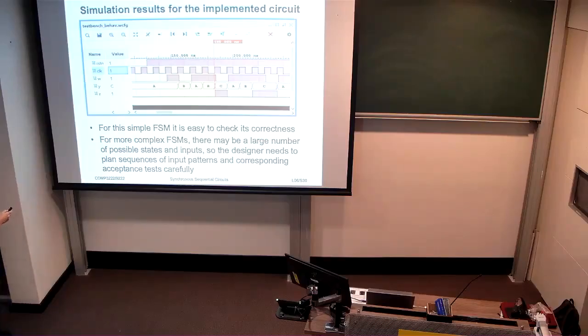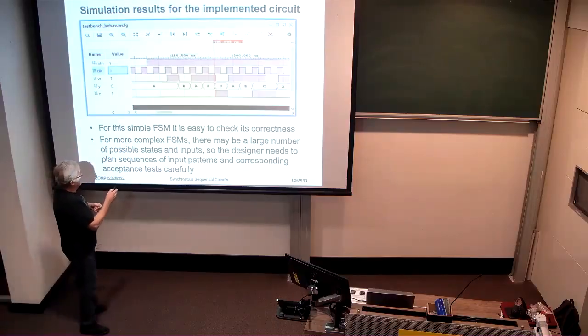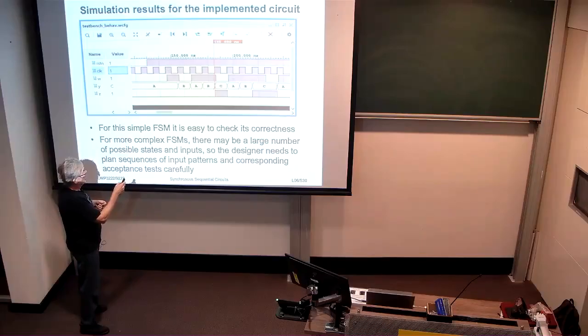The reset n is 0 initially, so that forces the machine into state A, and then it's 1 beyond that. We see our clock signal here, and we see the input W, right? Now, W goes high just after the rising clock edge here, and it's high while this rising clock edge comes along, and therefore the machine enters state B at that point in time.